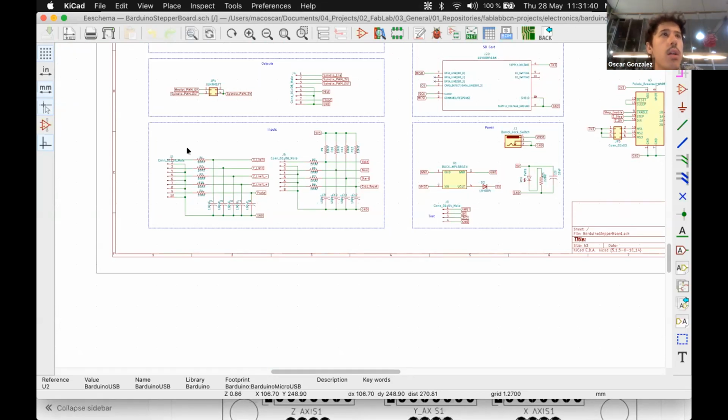Ed is saying that, you didn't get to know the ShopBot, but in the other CNC machine that we had here, you basically have a metal clamp that makes a short on one of the pins, and then you detect that you are on top of the surface, and that's how the machine knows that you've done the zero of the machine, or the bed leveling.